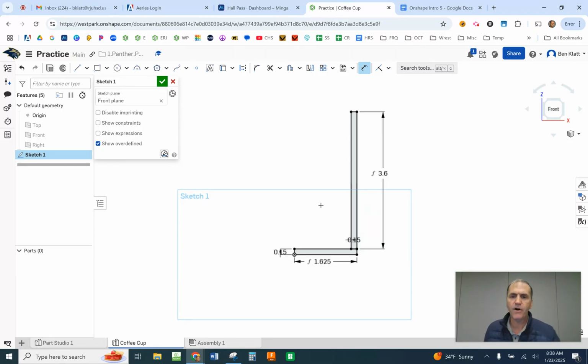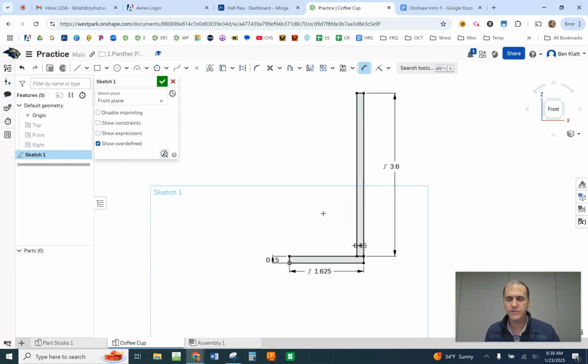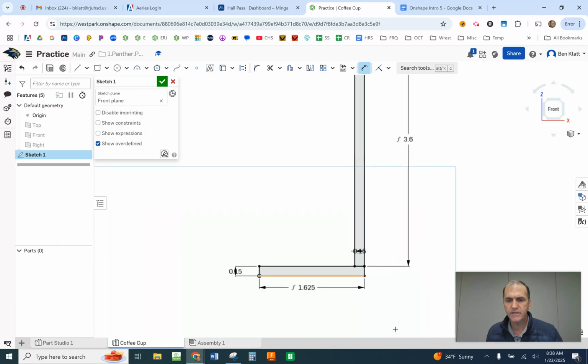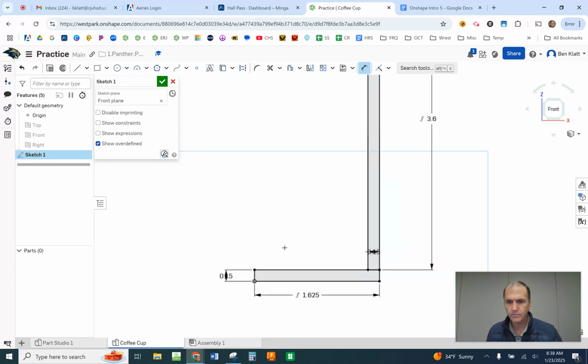Now we're going to use the revolve tool to make that. Actually, first, we're going to make some curves on this because the bottom is curved a little bit and the top. We're going to do this in a couple of different ways. One is we're going to fillet the sketch, and the other one is going to fillet the solid. Fillet is rounding over. You can either fill in or you can round over an edge. So let's go ahead and go in here, and we're going to fillet that edge.